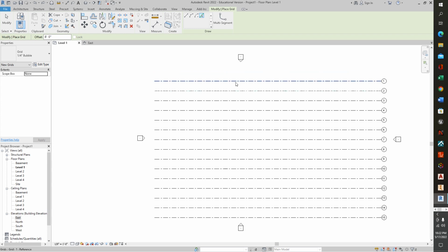So we've got the ones going from east to west, or west to east, I guess in this particular case. We've got that in there, but what we need to do is actually put some north to south grid lines. We'll go up into our ribbon again, into the draw menu, and grab the line tool, and we notice once again the angles there. We're going to want it to be 90-degree angles, keep it good at 90 degrees.